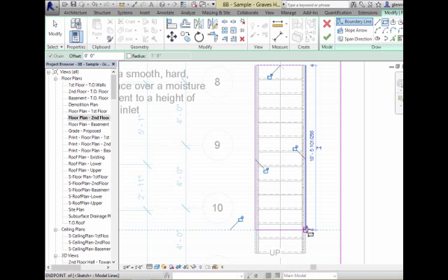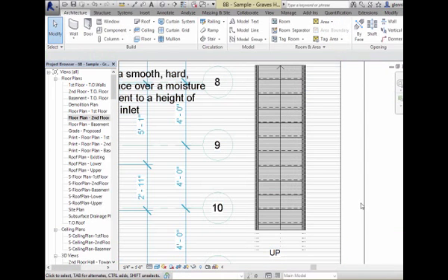What you do need to do is make sure that when people are walking up the stair that they don't hit their head. Okay, and the rule for that is that at any point, the opening has to be 6'8" clear above the stair so that you do not hit your head. And let me show you what I mean. Just put the hole in here. Okay, I got a hole there.